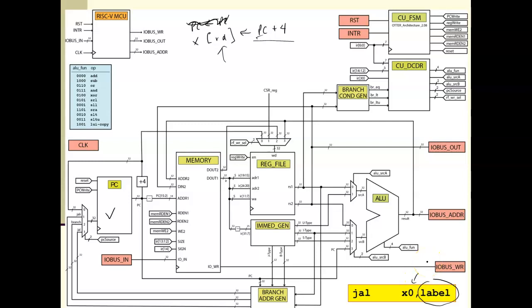So for this instruction, the execute cycle, I am going to do a couple things. So we kind of skipped over PC source and all the other instructions. It was 0, but in this instruction, this is the JAL instruction. PC source has to be 1, 1. Additionally, just like all the other instructions, every single instruction as part of that execute cycle, I'm going to set PC write to 1.